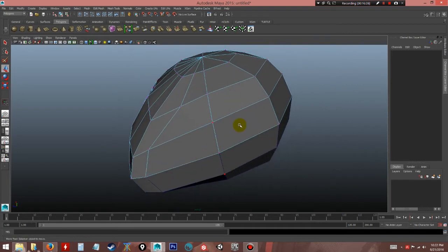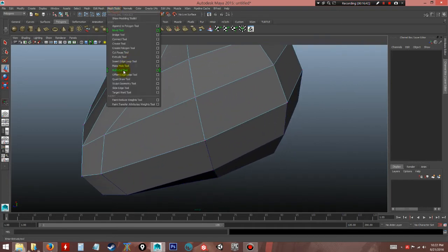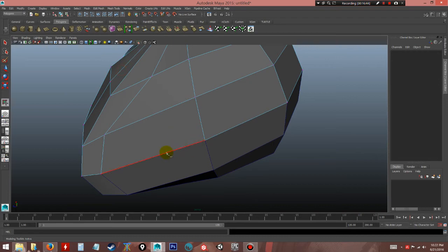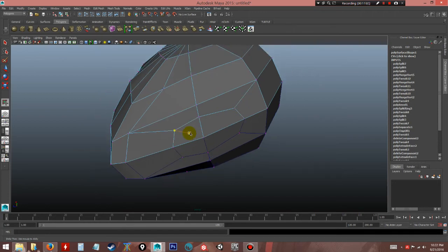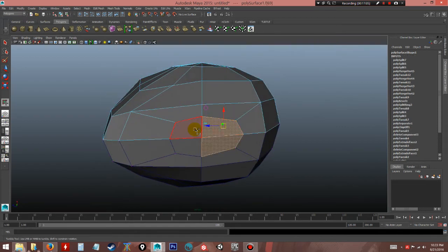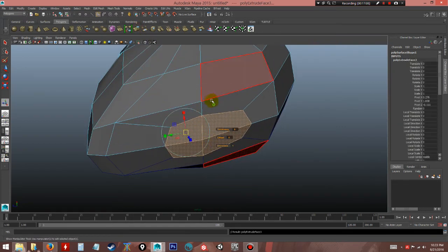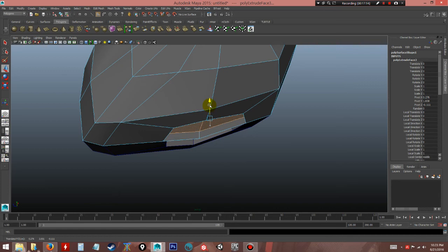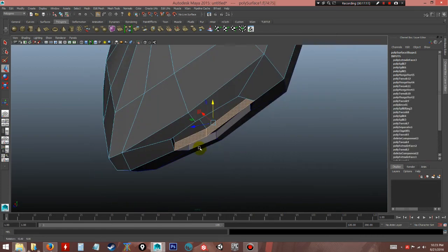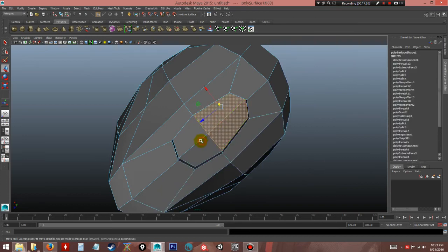And you can grow a neck hole from here. What you can do is use the multi-cut and cut away the neck hole like this. Enter, but then connect this to this edge to create four-sided, and four-sided here. So this one will be here. As you can see, all are four-sided. Then you don't need this, but just extrude this first. Extrude this inwards, switch to W and just move it upwards. It will create this center face. Delete that center face and delete the inner faces as well.